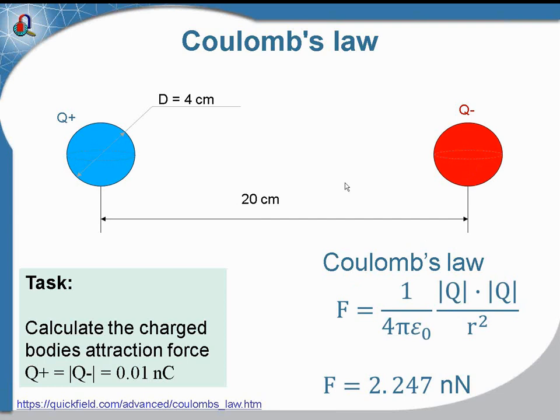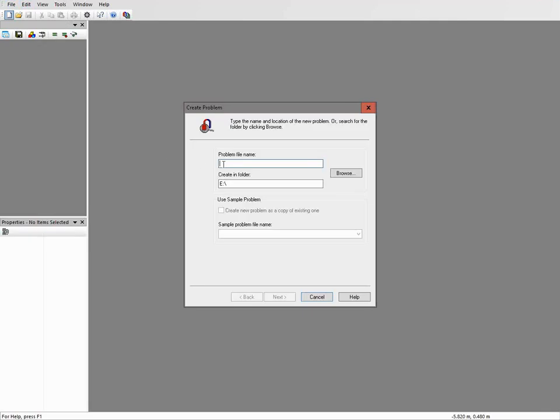For the configuration on the picture, with the charge of 0.01 nanocoulombs, the force will be 2.247 nanonewtons. Now let's simulate this case in QuickField. I create the new problem.